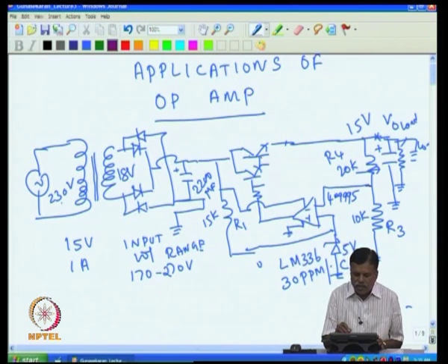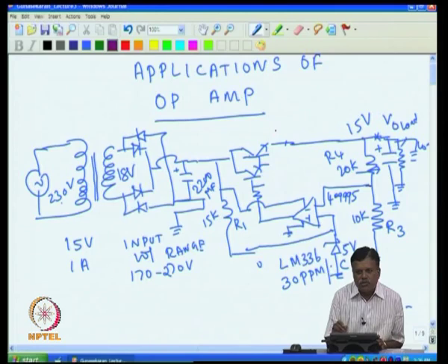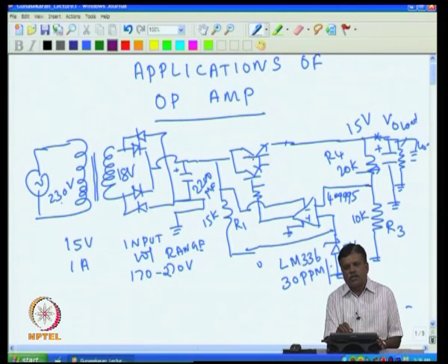At that time, this would have heated up, the junction would have gone to some temperature, maybe say 100 degree or 120 degree. Then you switch it off and go back, and at noon time you may switch on the TV again and watch the program. Again the noon time, this again will go back to 120 degree, and then you switch off, then this also comes back after some time to room temperature. The night again you will switch on and see the program, and again this temperature will go high, say 120 degree, and come back to room temperature.